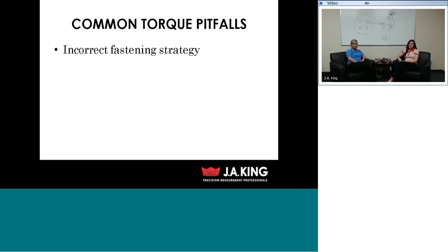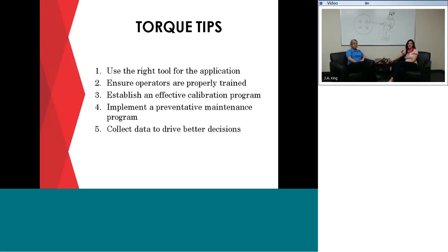Finally, errors can also result from the method that you use. For example, the majority of joints consist of multiple bolts that are bringing together two surfaces that aren't perfectly flat. If you don't follow the proper tightening sequence, it can result in an uneven preload distribution. So if you look at our fabulous drawing that one of our engineers did for us very early this morning, you can see the crisscross tightening sequence. Typically this is specified when you have circular bolt patterns. For non-circular bolt patterns, we recommend a spiral sequence, and then with that, you'll actually start in the middle before spiraling outward.